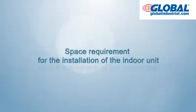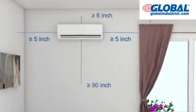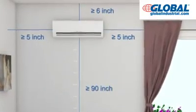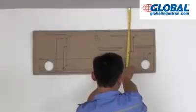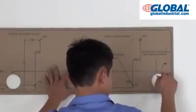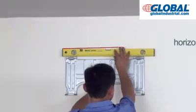Space requirement for the installation of the indoor unit. The right and left sides of the indoor unit should be more than 5 inches away from the wall. The upper side should be more than 6 inches from the ceiling, and the lower side should be more than 90 inches from the ground. Confirm the installation position of the indoor unit according to the installation manual. Confirm the position of the wall hole and the screw above the wall hole according to the direction of exit pipe. Fix the mounting plate.